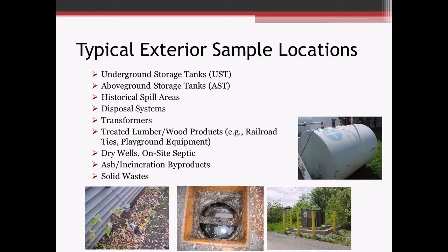So a big one is underground storage tanks. If you have an old underground storage tank that may or may not be active, you may have an issue with potential contamination from that petroleum product that might have been stored there. And that tends to be a costly cleanup if you do discover it, one that you may not have been anticipating. So always good to be aware if there's an underground storage tank before you start digging around the property.